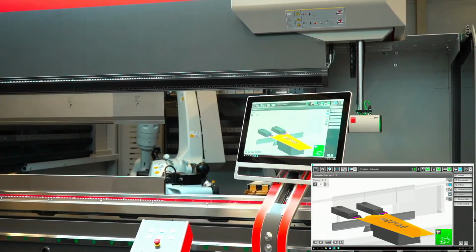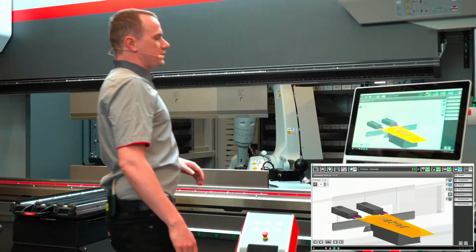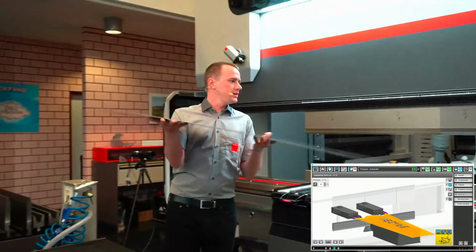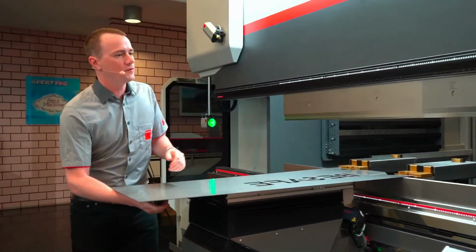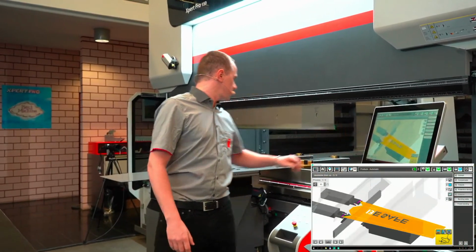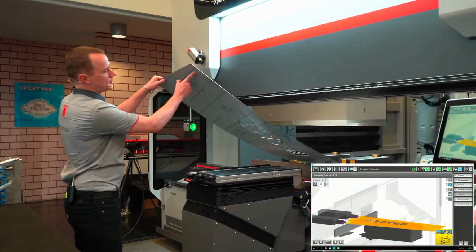So the first thing I'm going to do is bring the bending aid into position, push the foot pedal one time, and all axes move into their programmed position. And then I can very easily see how I have to put the part into the machine. Very helpful for this is our ByVision bending. So I can really see close up in which direction I have to put the part. I see the orange and also a blue side, so where we have plastic foil on it or not.